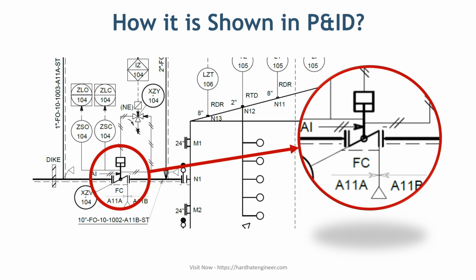In this part of P&ID, you can see a butterfly type control valve with a fail close setting. It is connected to a tank, so when there is a loss of signal, the valve will close to prevent the tank from overfilling. As mentioned earlier, letters like FC for fail close, FO for fail open, or FL for fail lock below the valve indicate its failure mode.